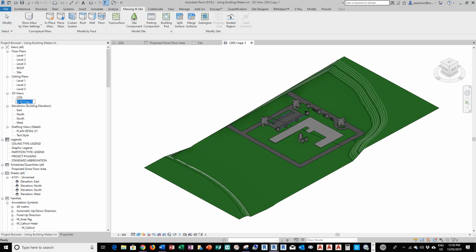view, and then we have to take out these curly braces because those are special characters which are not allowed when you create a new view. This is a default system 3D view, that's why it is permitted. So we're going to change this 3D view with mass,